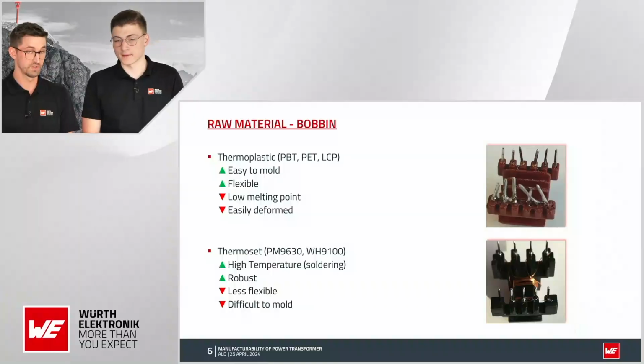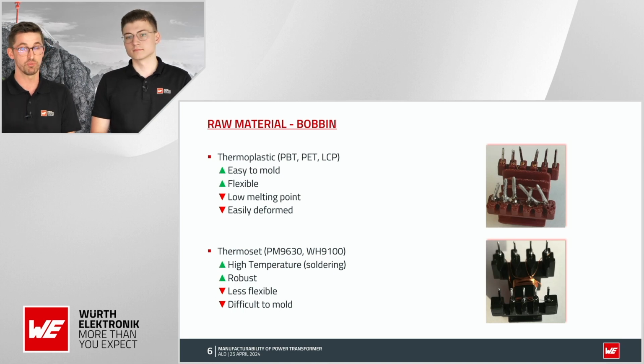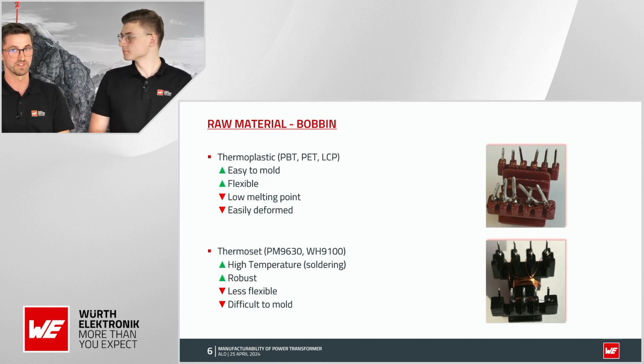It is a good question. So we have to keep in mind that this material has a lower melting point compared to the thermoset. So the time we submerge the bobbin into the soldering bath is crucial. So the first aspect we need to take into account is the time, and we need to reduce it as much as possible. And when it's not possible, we try to pre-strip the wire or to remove the insulation to make this process a bit easier. But as we see, most of the time, at least some damage is always present.